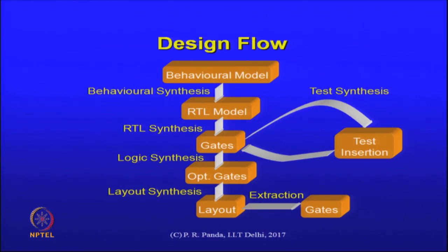Essentially, it may involve changing some of the existing flip flops into a more sophisticated kind of flip flop that can also be configured as the shift register that we were talking about. So, some of those flip flops, not all, because there is an area overhead associated with that insertion. But conceptually you have inserted some memory elements to help us in tracking later on. So, that is what is performed as part of the design step. All of this is technically performed by the designer.